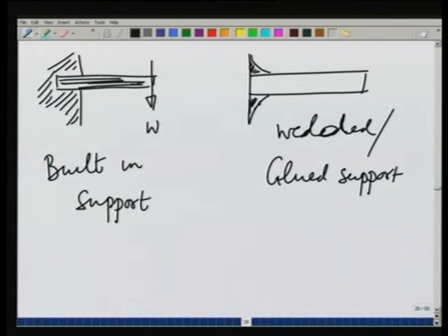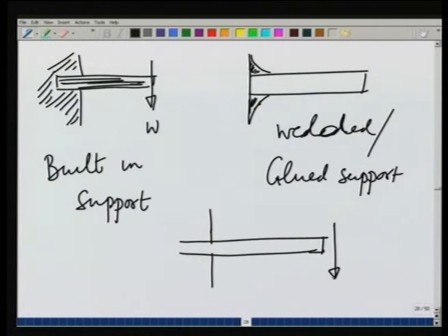What all are these capable of? To understand this, let us say I take this built-in support first and apply a load here, maybe hang something. Then you know this point tends to go down and this point will tend to move up. As the support pushes the wall down, there is going to be a force, let us say N1, the normal reaction of the wall on the support, and similarly this end is being pushed up. So, this would experience a force N2.